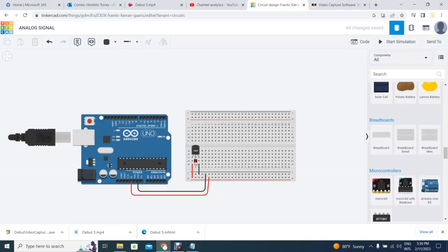The cable at the center is the one that needs to come right to whichever of these pins you want to use. Let's say that we're going to use A0. So now the voltage out from the sensor is going to be read by the Arduino. That's what we want. Basically, we are ready to have a small code written so that we can see the temperature. For this, let's program the Arduino very quickly. This is all that you need: the sensor and the Arduino.